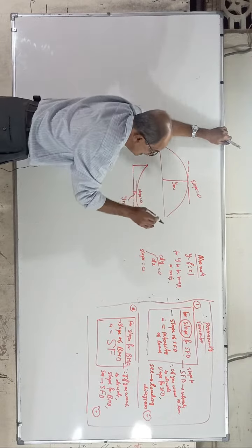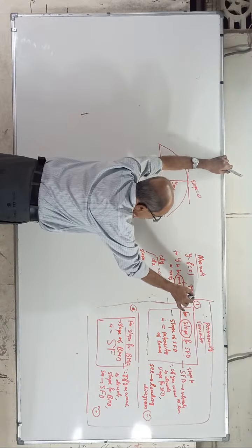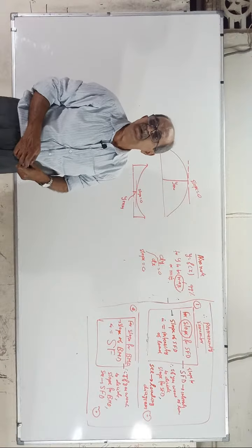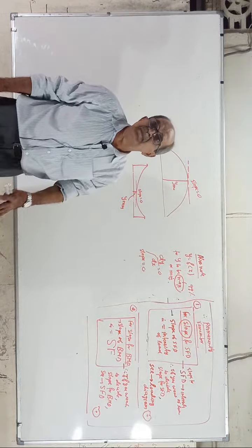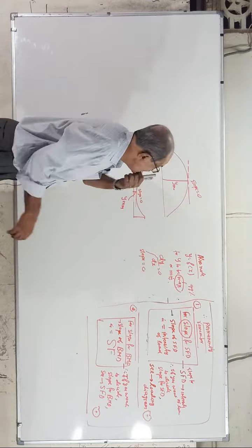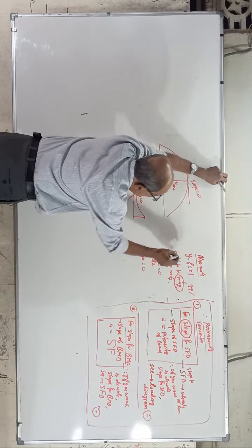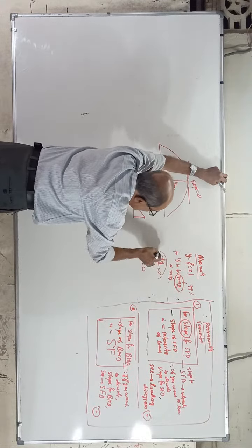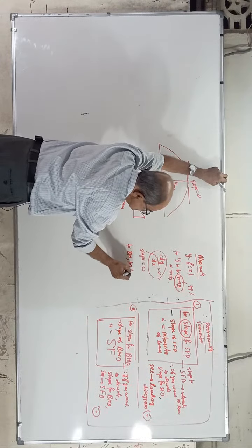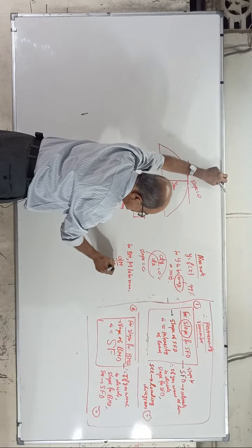Therefore, usually remember, maximum is very important. In 99% of problems, it is maximum. In rare cases, like overhanging beams, you get minimum. Otherwise, under normal cases it is maximum, and only under abnormal cases does it come as minimum. People will always tell maximum only. So, same way for y to be maximum, we know that dy by dx is 0. Same way for bending moment M to be maximum, dM by dx should be equal to 0.